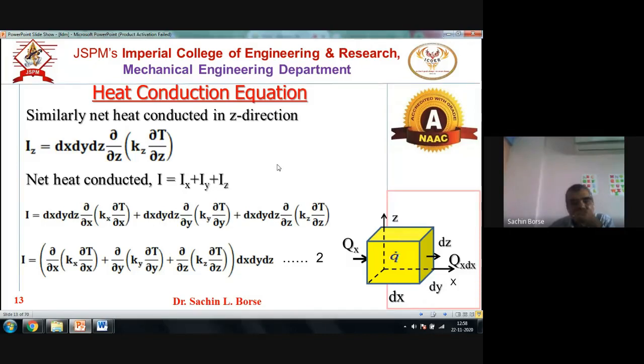So what I will do now, I will take dx dy dz common, and the other things I will write like del by del x into kx del T by del x, plus del by del y into ky del T by del y, plus del by del z into kz del T by del z, into bracket, and then dx dy and dz. So it is the net heat conducted. Can move further.